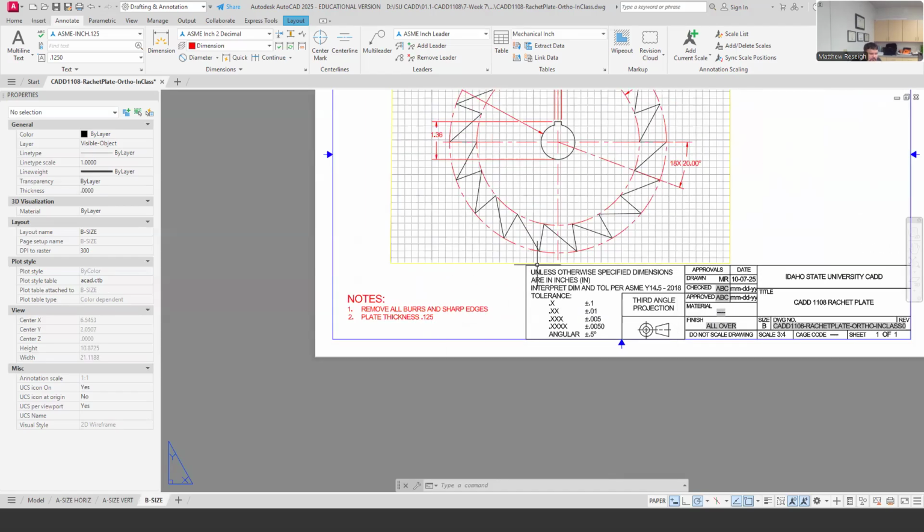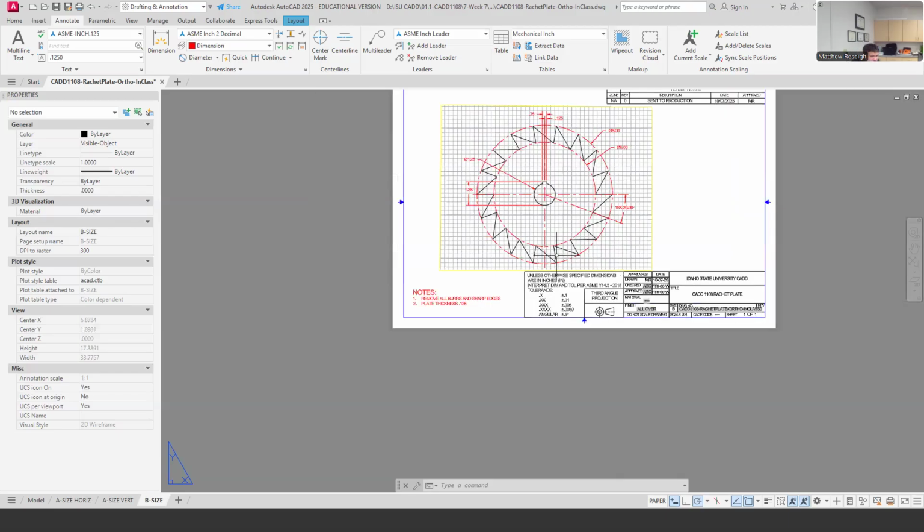So I can make a multi-line text that has the initial line as the title, usually the title of the part or a part number, and then its scale and whatever else information you need to carry. That's how you would have multiple parts on one page, is definitely title them. It might be a single title, even if it's multiple views of a part, and I can fit multiple parts with multiple views. I'm just going to title probably one of the views, maybe the front view usually, and I don't have to title all my views.